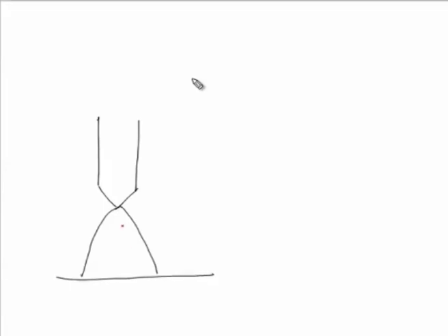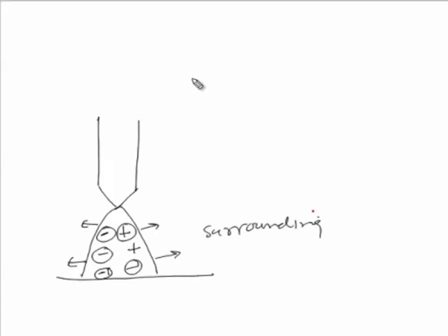The welding arc involves the flow of current through charged particles. Once the arc is ignited, the flow of current will start, but in the process of welding, these charged particles are lost to the surroundings, and some of these charged particles are lost to the base material. So, these losses of charged particles must be compensated,